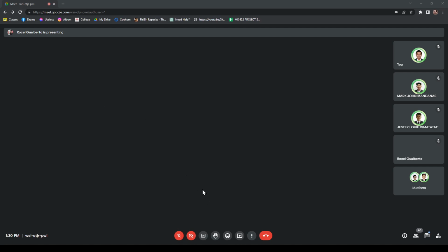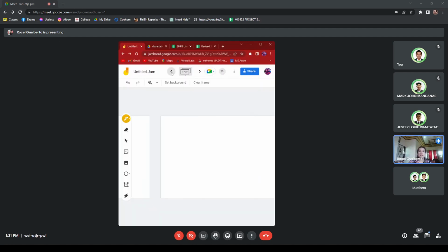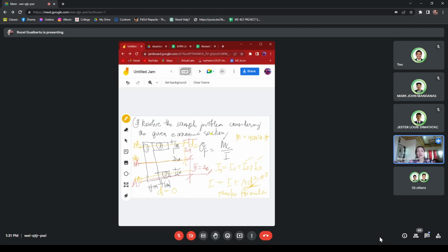Okay, so this is correct. We have I total is 10 inches to the fourth, and the flexural stress is 10,800 psi or 10.8 ksi. Put your answers in here. Okay, good. The others, kindly solve and put your answers here, then we will continue. So we have the flexural stress. Let us continue.